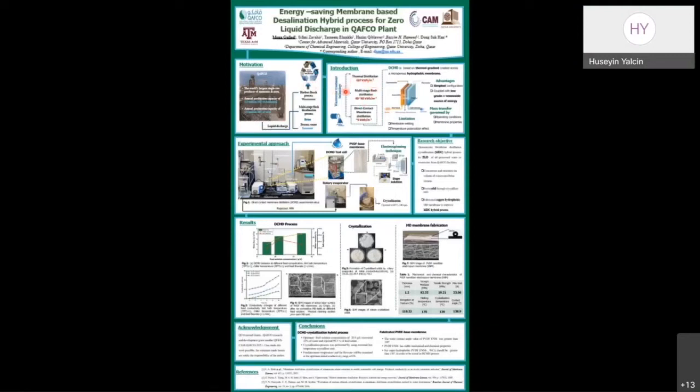To tackle this issue, we can use a conventional thermal distillation process. However, these processes are known for their high consumption of energy. As an alternative, we can use the direct contact membrane distillation process as we propose here. So what is DCMD? The DCMD process is based on a thermal gradient created across a microporous hydrophobic membrane that allows water vapor molecules to move from the hot side to the cold side where the permeate is collected.